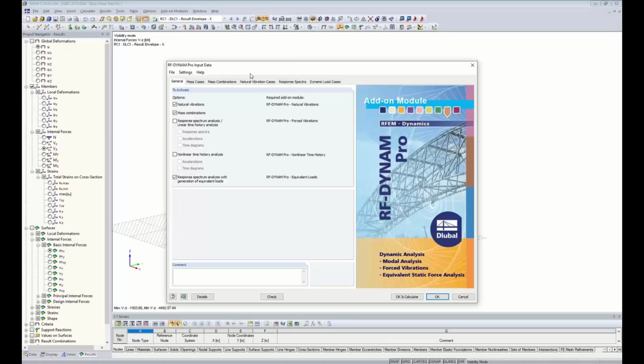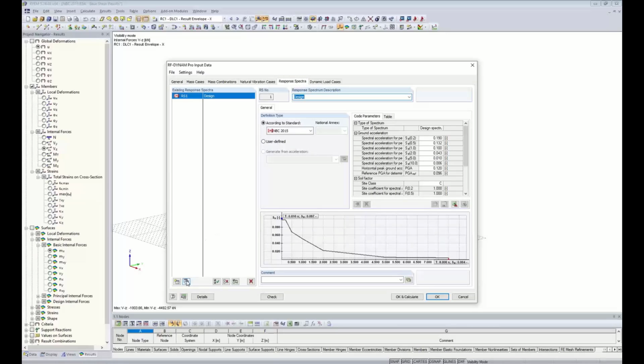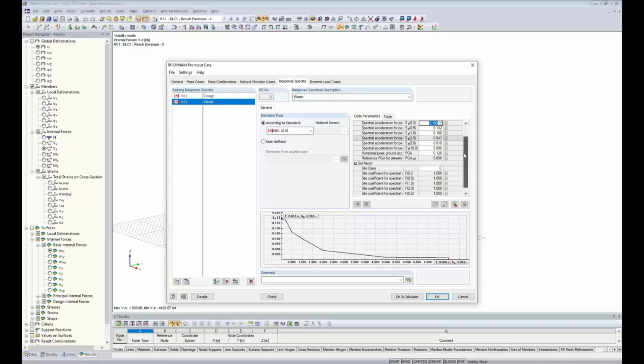The last thing I want to do is just, like I said, discuss these drift or deflection considerations. So as we just saw within the PowerPoint, what I'd like to do here is to make a copy of my existing response spectra, and we're going to rename this one elastic. The type of spectrum, as we just talked about in the PowerPoint, is going to be elastic response spectrum. So now notice that all of this information was copied from my previous case, but I'm no longer asked for the variables IE, RD, RO. This is taken out of this consideration, so no factors at all.